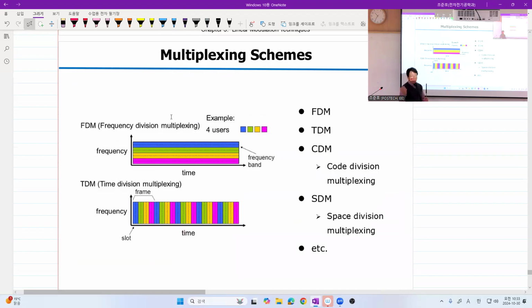So even though time is closely related to the frequency, if we use Fourier transform, actually we may use its variation called short time Fourier transform. What does that mean? Short time Fourier transform simply understood as you first mask the signal so that your signal of interest is within some short interval, and then you apply Fourier transform. In that case, your single signal or multiple signals can be viewed not only in the time domain and at the same time frequency domain, right?